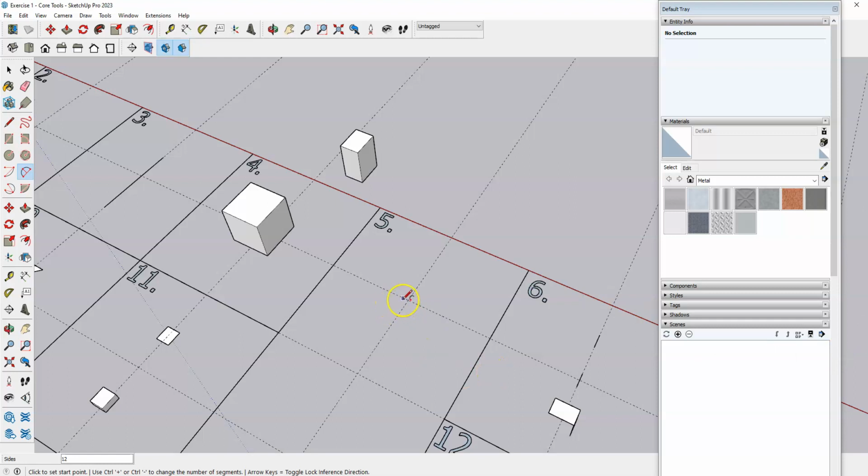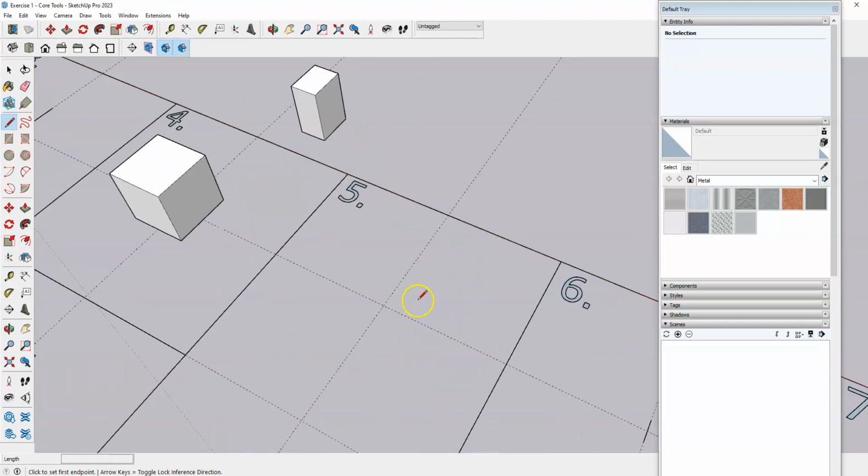So in box 5, we're going to do a couple things here. The first one is to create a line that is 6 inches long. So you select your line tool or hit L on your keyboard, and it wants to be 6 inches long, so you just choose a starting point. I don't specify in the assignment where to start at. I'm just going to start at this intersection of grid lines here. So click once to start.